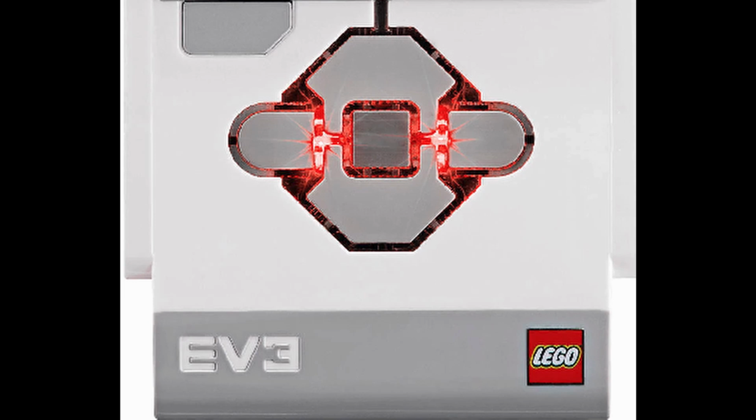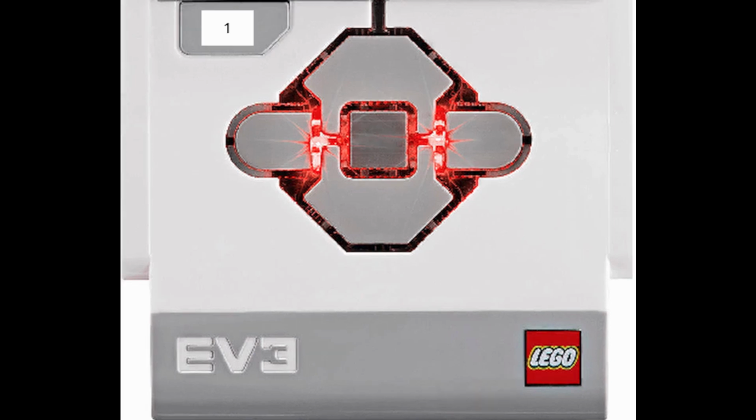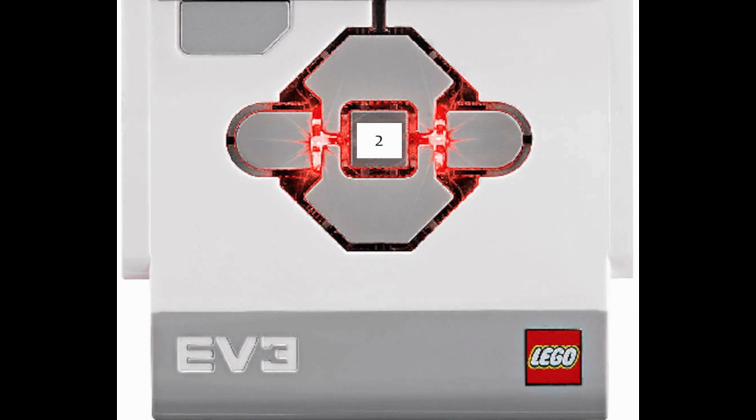On the front of the EV3 Brick, there are 6 buttons. The first one, located in the top left corner in the area below the screen, is the back button. It primarily undoes actions, stops programs, and allows you to turn off the robot. The second one is the center button. It is the one located in the middle of the area below the screen, surrounded by 4 other buttons. It allows you to select the options of the EV3 Brick, run programs, and turn the robot on.